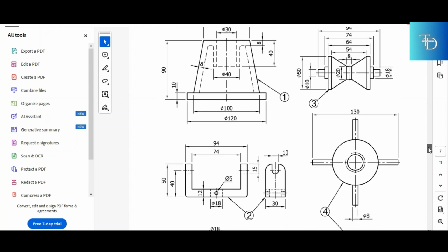So now let's shift over to part number three. Part number three is the roller. And remember, with the roller cradle, this is the roller, which means somehow this roller should be able to fit on the roller cradle right there. Focusing on the side of the roller itself, it has diameter 10 on the sides. Those tiny rods right there, they are of diameter 10. You go toward the roller cradle, you have a diameter 10 space right there. And this opening of diameter 10, there's two of them because this is the front view of it. The side view looks like this, which means on the side also it looks like this, just like I've shown you on the 3D view.